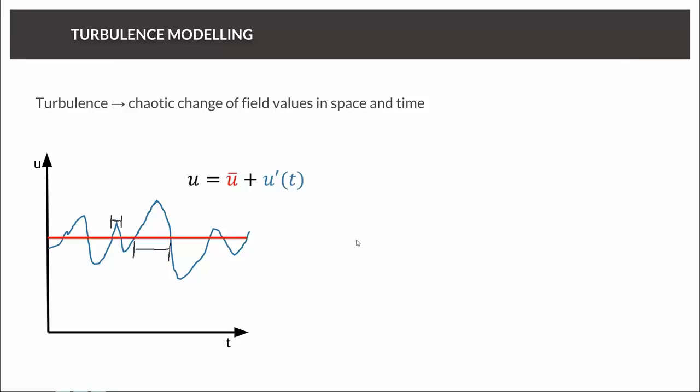And since usually you have a high bandwidth of different time lengths, it would become a big problem if you would really try to calculate the turbulent flow around a Formula 1 car. Actually, I would say it's not possible. And therefore, what you do is use a turbulence model. And here the approach is very easy. The first idea is, what if I average my flow or my quantity, and then replace it by the average value plus a function which is representing the oscillation, this one.